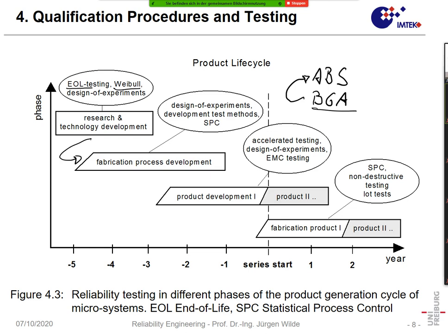That means now you can produce in your factory test samples, and here you can investigate how a printed wiring board assembly process with BGA can be accomplished. So here we could say, for instance, BGA on printed circuit board. What will be the result if there are soldering defects and so on. So here we do a fabrication process development. And that's in our factory line.